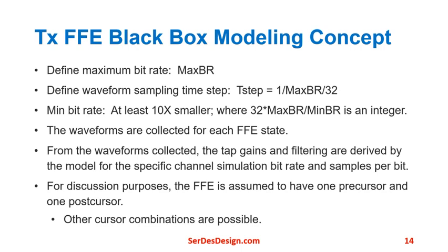In the derived IBIS-AMI model, the tap gains and filtering are derived from the waveform data for each simulation for the specific channel simulator bit rate and samples per bit. For discussion purposes in this webinar, the FFE is assumed to have one precursor and one postcursor. Other cursor combinations are possible.